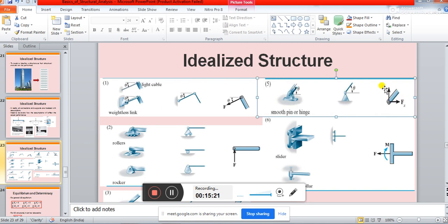Is it clear? Now, if you come to the roller support, you see this is a typical type of roller support. Rollers can be of different types. Ideally, when you observe practical problems, your rollers may look something like this. See, three roller supports, then there may be some kind of rolling mechanism given like this, and there may be some kind of rocker support, which will be able to move in this direction and this direction.